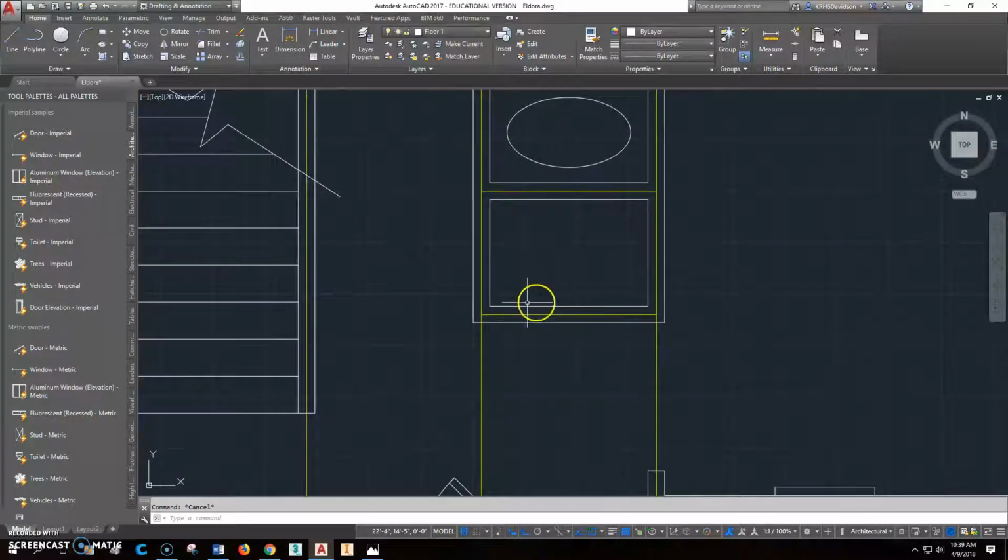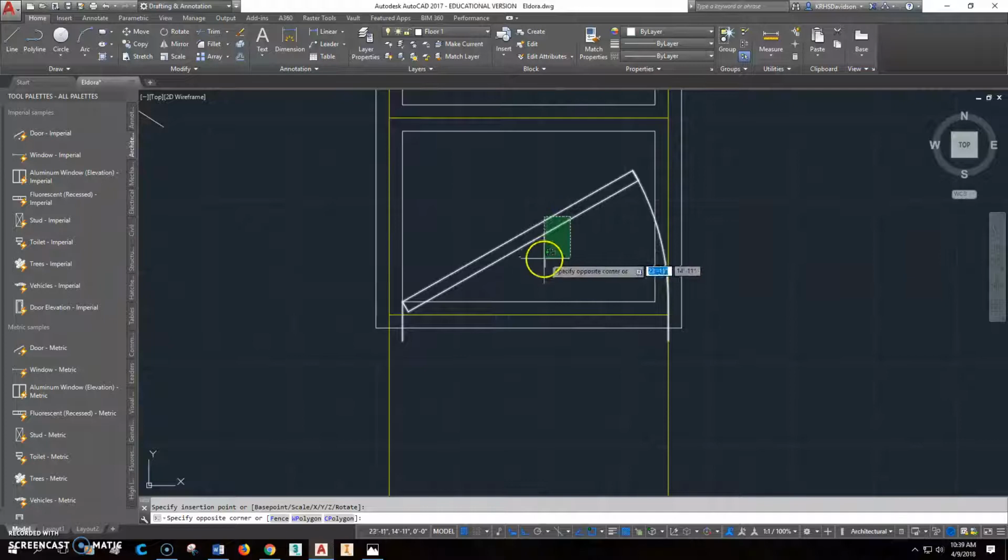There's also a door right here. So the distance across this opening is 3'2". We're not going to want a 3'2" door. We're going to want at least 2 inches on each side of it. Minimum, probably closer to 4 if we can get away with it. So let's put a door in here. Let's see, we'll put that right there. And now let's go pick a door that goes, let's see, 2'8".